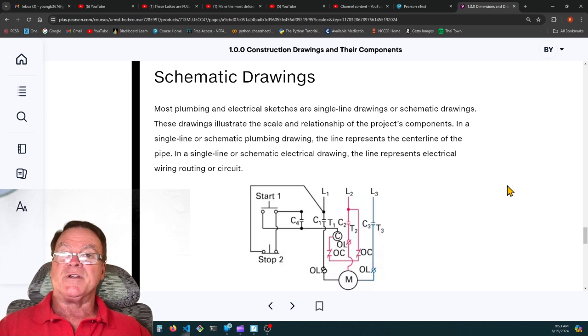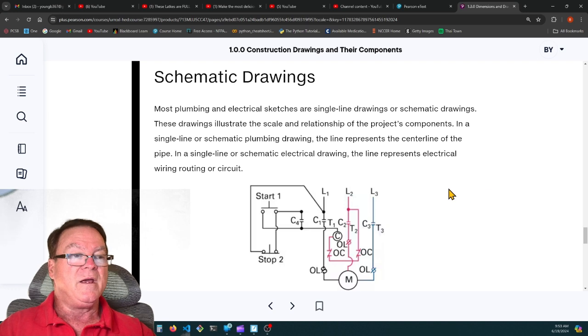if it said a quarter inch equals a foot and something measured 20 feet, you could measure it and see, yes, this is right. This is 5 inches times 4 feet per inch. So this is 20 feet. It was scalable. The other was not scalable. You'd have to use a multiplier like 0.936 or something. You can figure it out, but it's a heck of a deal to have to go through.